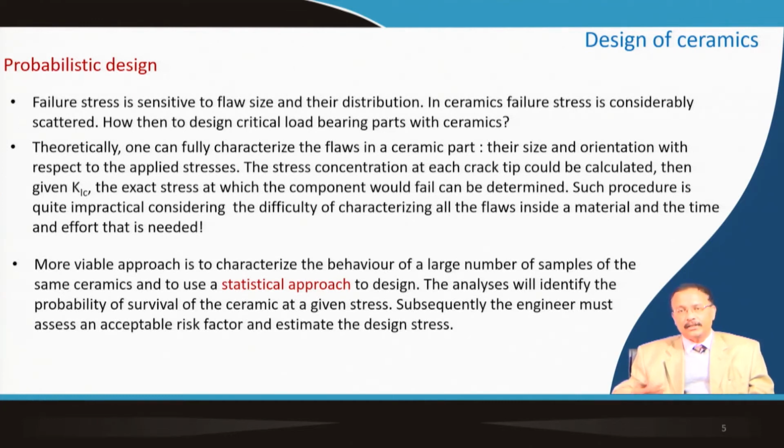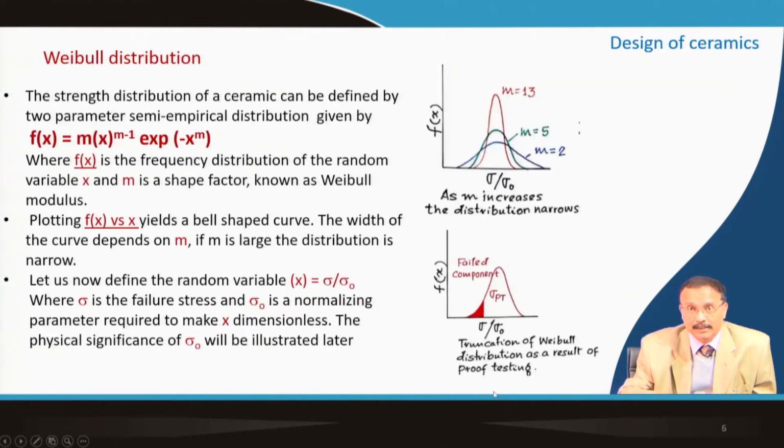So, you know what stress is required for your application, and you will have to identify the probability of failure of your material. Subsequently the engineer will assess whether this kind of design stress is good for his application, and then accordingly he will decide whether the particular ceramic is of any use for practical purpose.